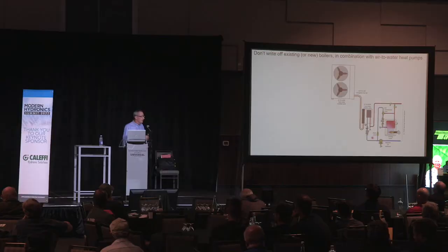So you can keep that conventional boiler, assuming it has service life left to it. You simply have to add an anti-condensation valve. And what that does, on cold conditions, it will recirculate the water coming out of the boiler outlet right back into the inlet. It brings the boiler temperature up quickly above dew point, and then it allows that energy to flow out to the system. So basically, the heat pump and the boiler are in parallel. So a control system could call either one to operate.